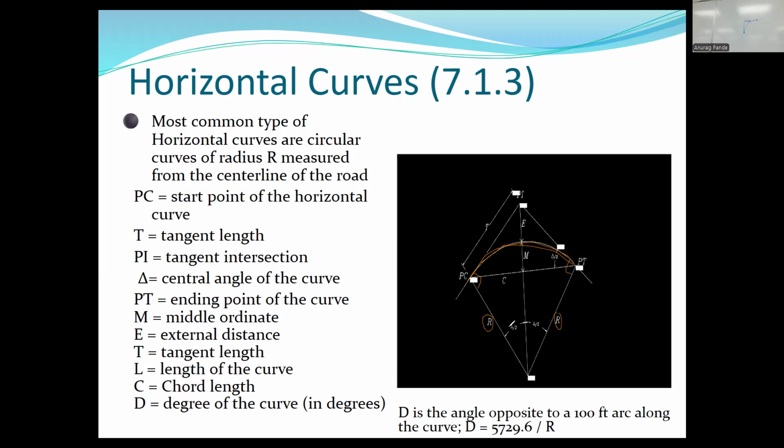Then we define something. It's this angle of the circular curve. We call it delta, right? So that's the delta angle. So if I ask you, what's this angle? If this angle is delta over 2 and delta over 2, it's a symmetric situation here. So delta over 2 and delta over 2 is delta. What's going to be this angle right here? Anybody know? And I'm looking for that in terms of delta. 180 minus delta, right? That's exactly right, because you can see that these two angles are 90 degrees.